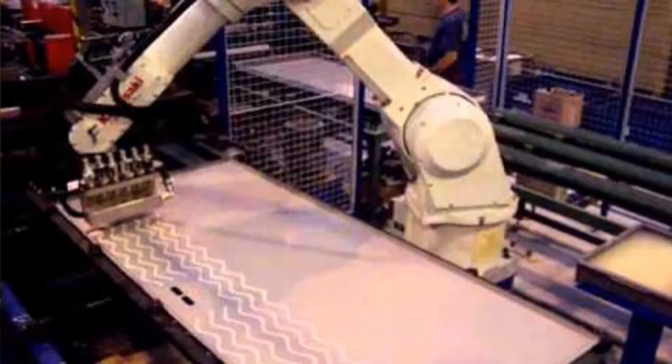So controlled path is a lot more precise way to control your robot. Here's an example of a robot performing an application. It looks like they may be printing something or possibly spreading glue down on a sheet. When we think about what kind of path we would need for this, point to point would certainly not be a great path. If we told it to move point to point, the robot would just start here and go in a straight line to here. Otherwise, we could program in a bunch of tiny zigzag points, but this looks like a smoother line. So we know this probably isn't using point to point.